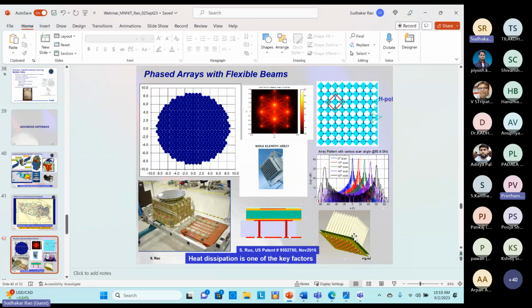Sir, can you suggest substrates which can be used for the design of antennas? Normally, we go with the Rogers material, or for a comparison, or if it is going to be flexible, polystyrene or a jean material. Can some other substrate be used for research work, sir? FR4, I think people use because it's commercially available and it's cheaper. Yes, sir. FR4, to be different, you can use it. RT Duroid 4003 is also used quite a bit.